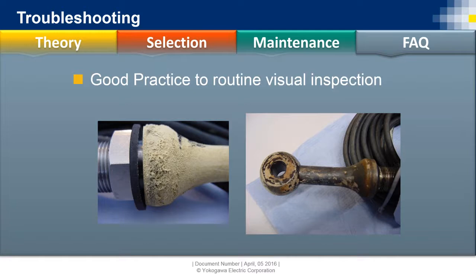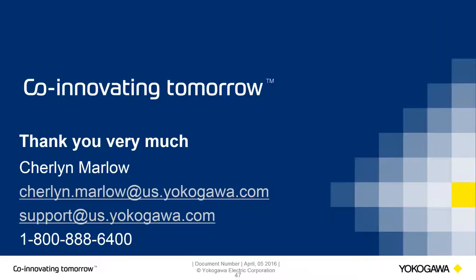And these are pictures of two from last year, where they finally failed after 10 years, and they said it's not working. They pulled it out and sent it to me, and that's the condition the sensor was in. There's a reason why it's not working. That's supposed to be brown, or a PEEK gray, or I guess a tan material, instead of black. It was the same thing: the process was physically attacking the sensor material. So if PEEK is not compatible, like in sulfuric acids, we need to make sure that we use Teflon. So just be sure to check them and make sure we pick the right materials for the right sensors.